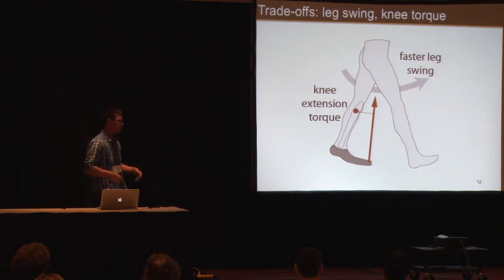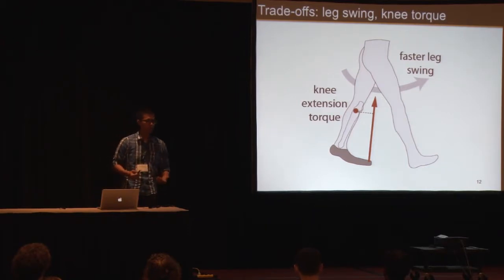Another thing is, if we have a longer foot, the moment arm of the ground reaction force about the knee joint is longer, so it will cause more knee extension torque, which should be really uncomfortable to walk with.